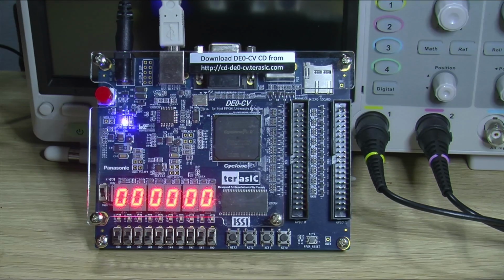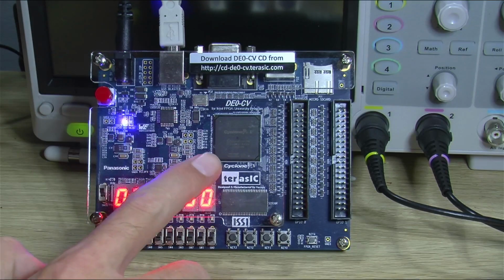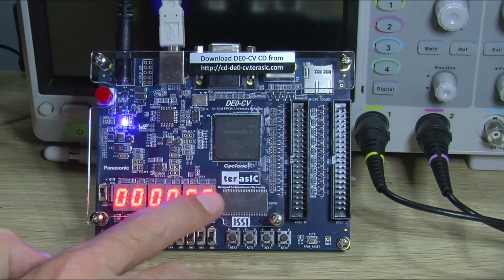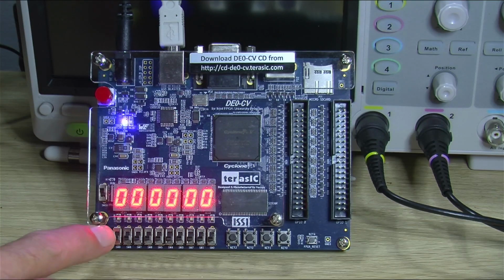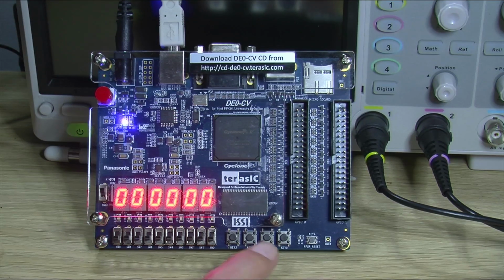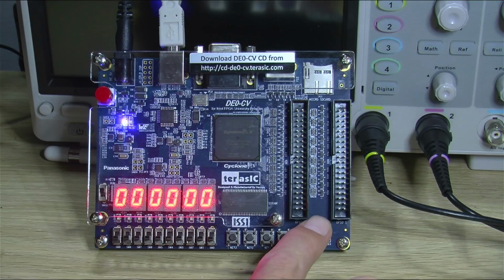But basically what this board gives us is the actual FPGA chip itself. We've also got some SDRAM that we can play with as well to be able to store stuff. As far as simple input and output, we've got our 7-segment displays, so 6 of those. Below that we've got 10 LEDs, 10 switches, 4 little push buttons, a bunch of GPIO, which we can use similar to GPIO in microcontrollers, but all of the stuff done with FPGAs is digital. So there's no analog to digital converters or stuff like that, although we can hook them up to the FPGA if we want to.